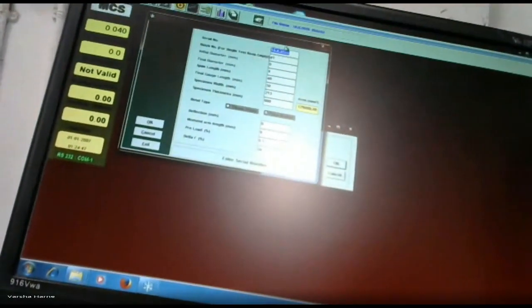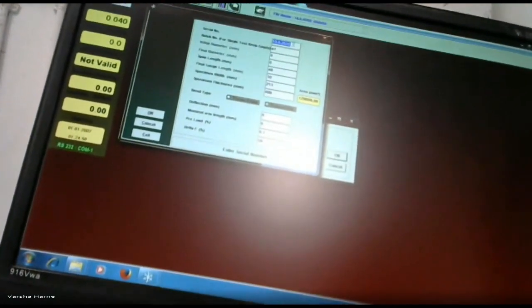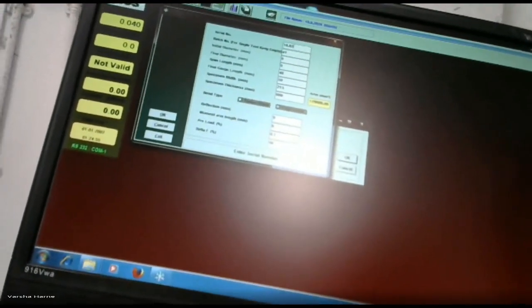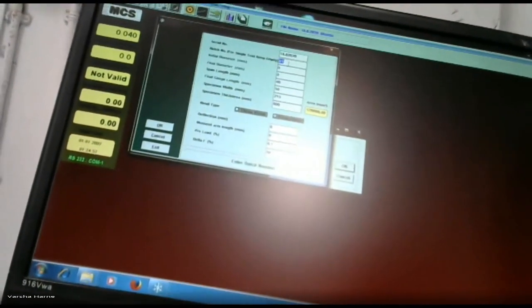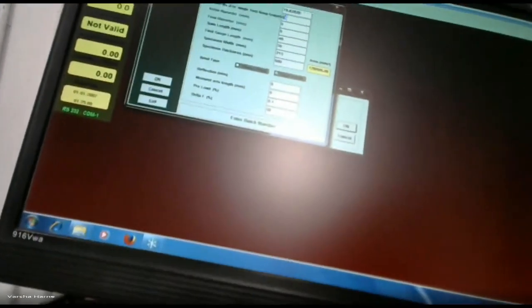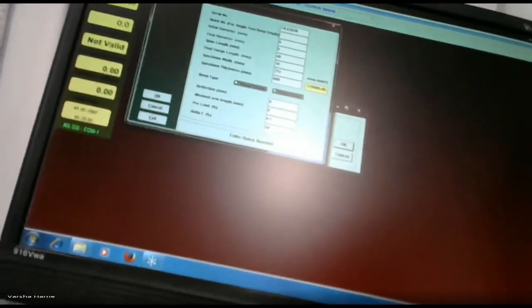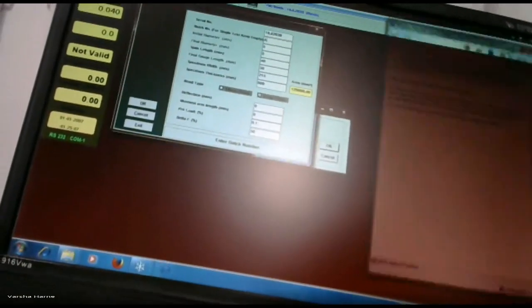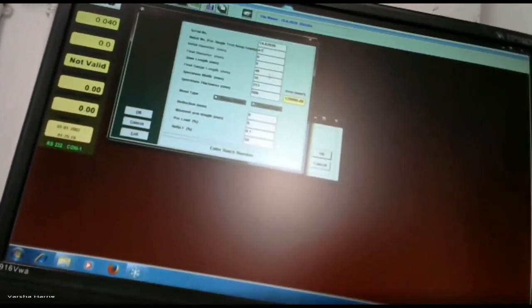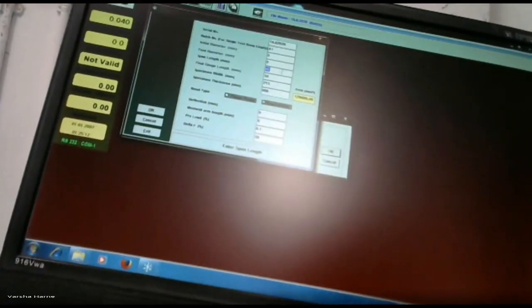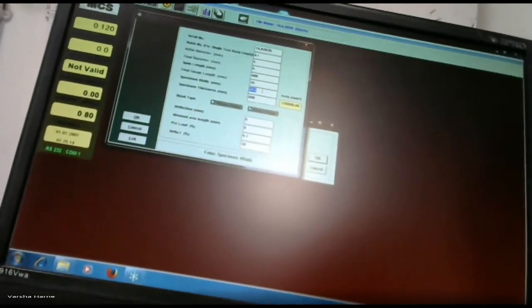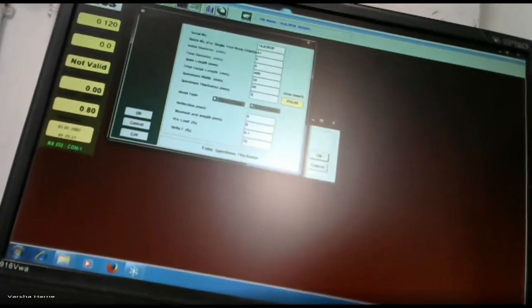So which type of bar is there? Flat. So you have to put in our parameters. Here the serial number, and today's date is 18.8.2020. Batch is capital A1. Then the span length, we require only the support to support distance, that is 400 mm. The width of the specimen is 50 mm. Thickness is also 50 mm.